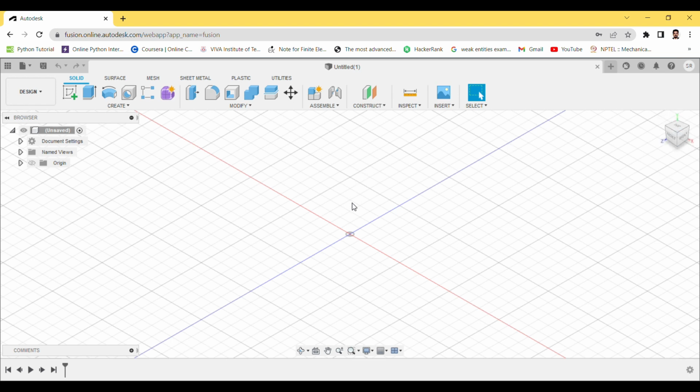Now in order to create the 2D sketch, since cylindrical jobs are symmetric along the horizontal axis, I'm going to create a half sketch and revolve it. So I want the Z horizontal and I want the X or Y vertical.